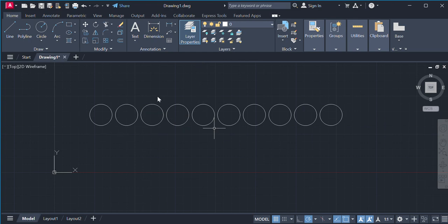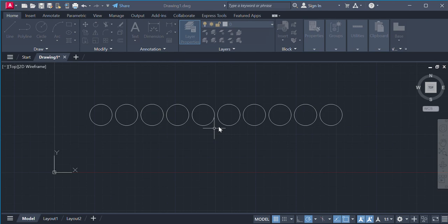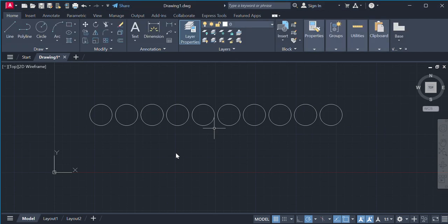Right? Let's say you had specified a layer for fence and then you want a specific type of line for your fence. Then you would come here and add fencing. If you wanted red, that's fine. Then you load. Then you would come and look for your fence line here, depending on the type of fence line you're trying to use. Remember to select it, then you would have it on there.